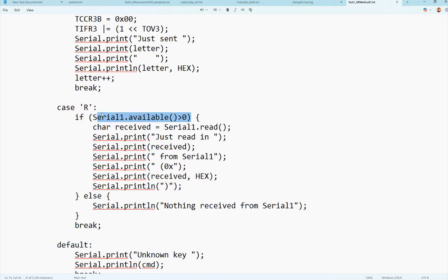So over here, if something is being received and this one becomes available, that means the UART receiving interrupt will be triggered, even though you are not writing it yourself, but behind the scene it's being received, and this will become 1, right? And then this is getting satisfied. It comes in, you read it. Okay, you read from the buffer. You read from the buffer.